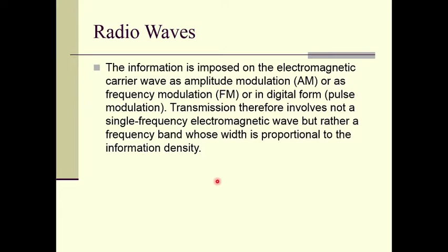So, the amplitude of the voice will be modulated in that frequency, and that is called amplitude modulation. That means the amplitude of the transmitted wave will vary, and accordingly we can listen to the voice of the singer on our radio sets, right. So, when we tune our radio set to that particular frequency, for example 500 kilohertz, right.